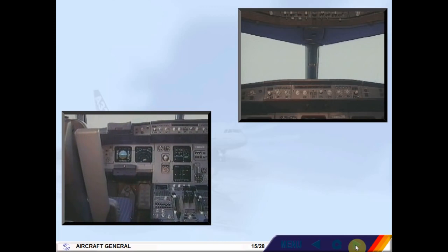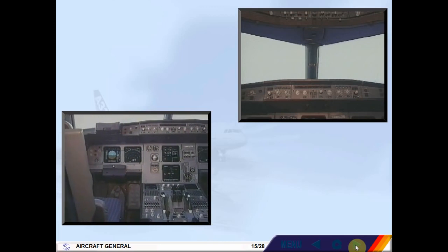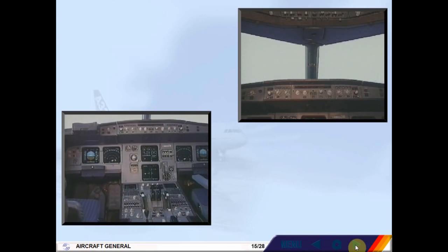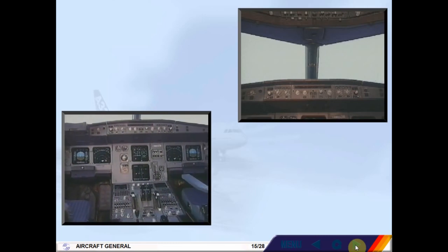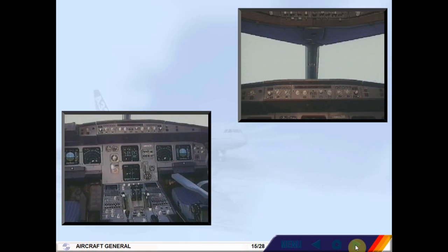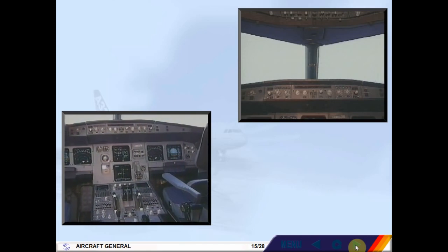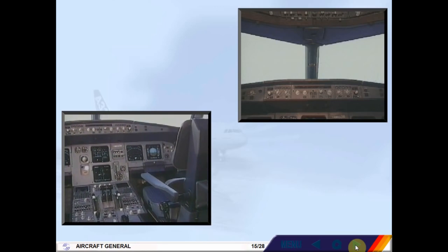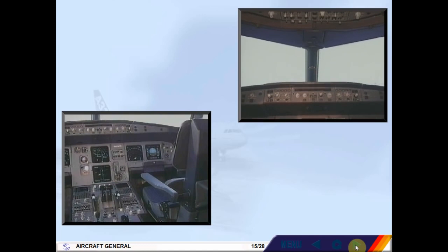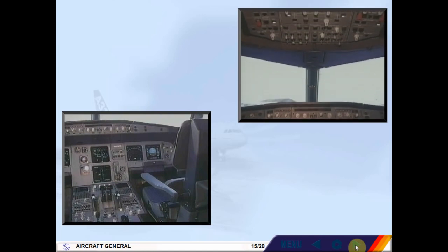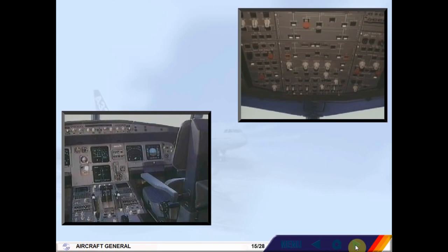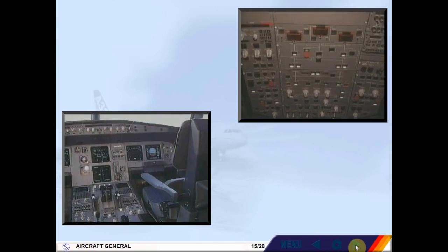The cockpit of the A320, a 2-man glass cockpit, is the most advanced cockpit of any civil airliner. It has an optimized layout of 6 CRT display units. The absence of control columns between the pilots and instruments ensures excellent visibility of all instruments. The system controls are located on an overhead panel in such a way that both crew members can monitor them.